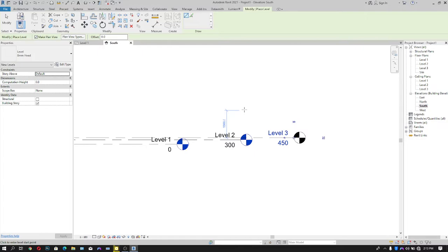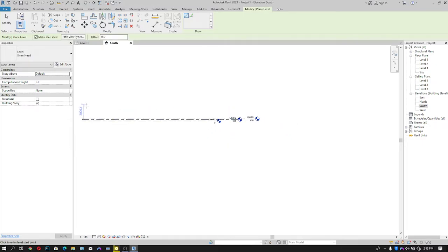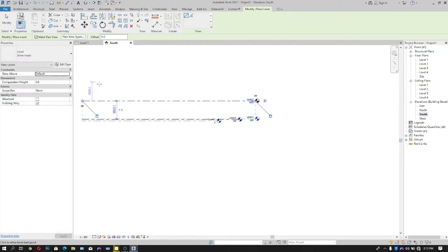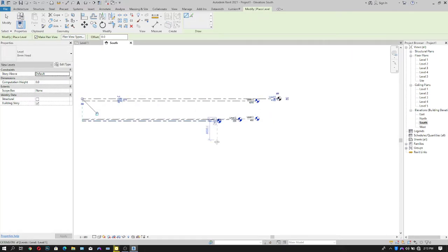The same way you are going to do for your headroom height, LL. Go to the left hand side and type in, let's say, 3800 and click it. Now for our concrete fascia, which is 450, type in 450 and drag it to the right hand side.